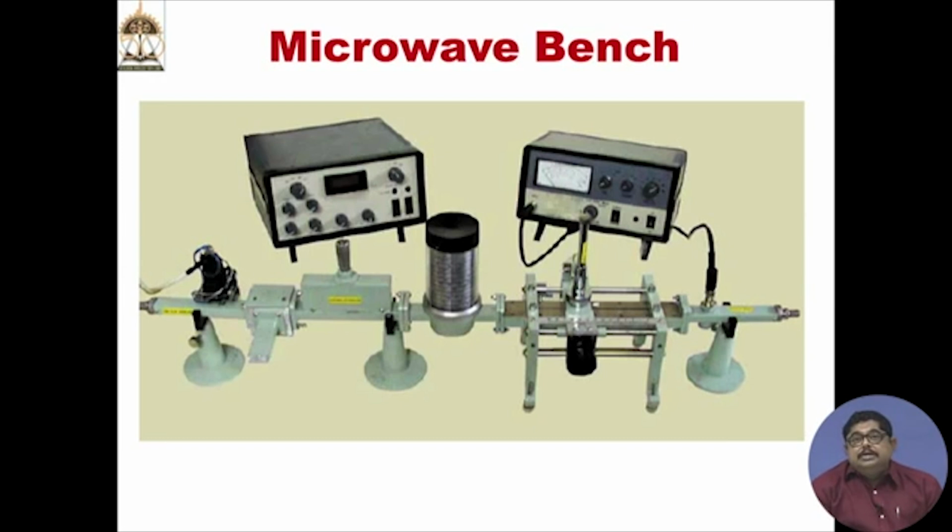That is why there is a waveguide with a slot cut at the central portion of it, through which a probe is inserted, and that probe, which is basically a point contact diode probe, is connected to a meter. This is a new thing, called a VSWR meter. So, there are two boxes you are seeing. The right one is the meter where you see various parameters, particularly VSWR, which will come next, and the left side is the power supply for that klystron source.